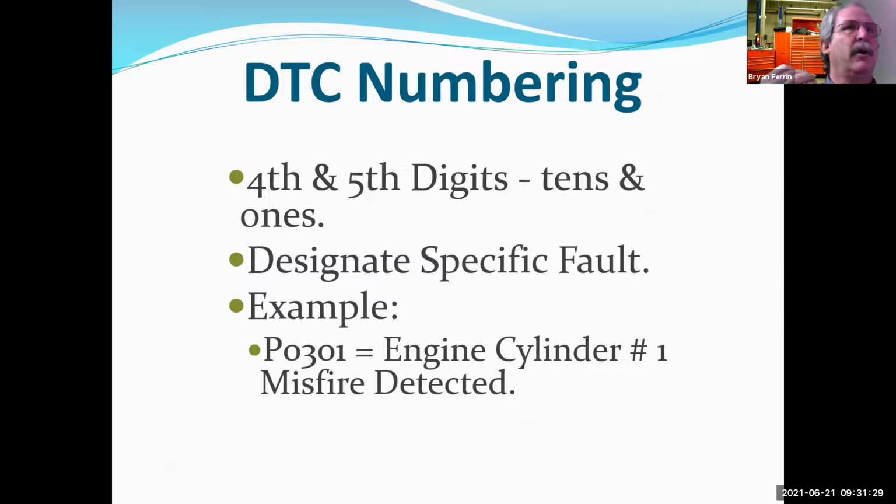Another example would be a car like a Saab that uses ion detection. I have cylinder misfire codes. When I check the spark plugs, I find that someone put aftermarket spark plugs in with 4 ground electrodes instead of the single ground electrode. It uses ion detection, and it has completely messed up the ion detection. It thinks everybody's misfiring. The car's not misfiring. Someone put the wrong spark plugs in it. That makes sense because they're using the spark plugs for the ion detection. They put the wrong ones in. It'd be like using a meter with bad leads.